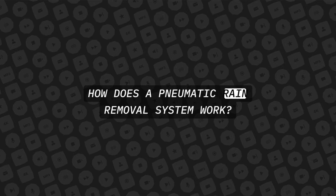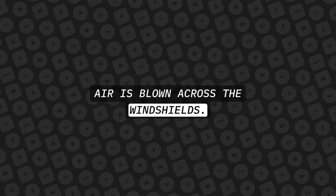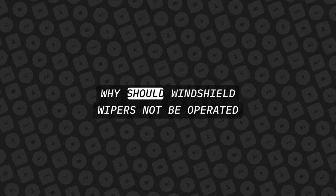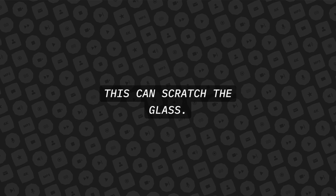How does a pneumatic rain removal system work? This method uses high air pressure. The high temperature engine compressor bleed air is blown across the windshields. This air blast forms a barrier that prevents raindrops from striking the windshield surface. Why should windshield wipers not be operated when the windshield is dry? This can scratch the glass.